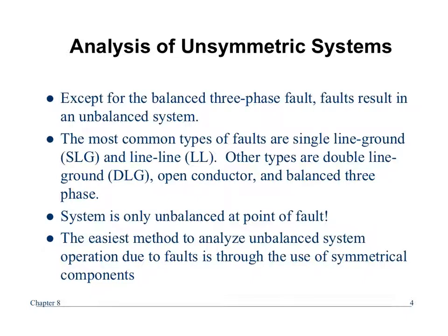Keep in mind that also can raise the voltages on the unfaulted phases, right? Because if you have a phase to ground fault and you don't remove that phase to ground fault for an extended period of time because you have very little current flow, then the phase to neutral is going to be much, much higher because neutral now is at the same potential as one of the phases. So some of the protection schemes you have to look at is how much voltage or how high will the voltage be on the other phases before damage will occur, okay? So generally you try to limit them to fairly short time.